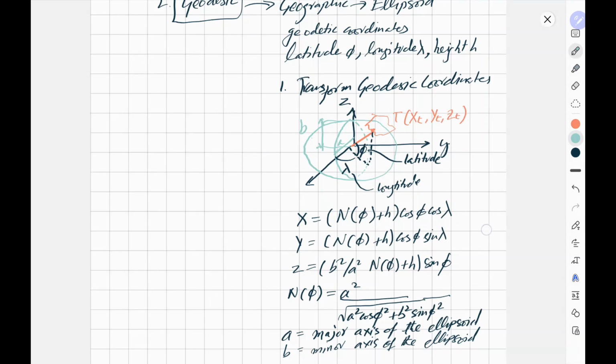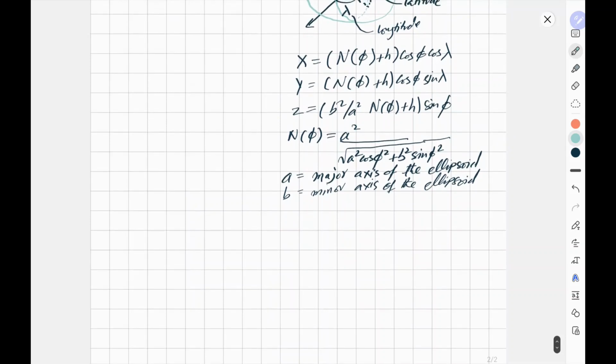So what happened is that if you use these equations, you consider that your earth is ellipsoid like this. This is a portion of that, okay, and your surface, earth surface, topographic surface is somewhat like this. So what you do is that you take a tangent over a point, okay, and this is known as a tangent plane, and it will have some height.